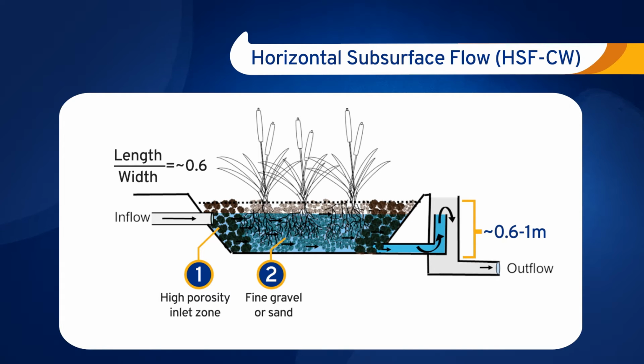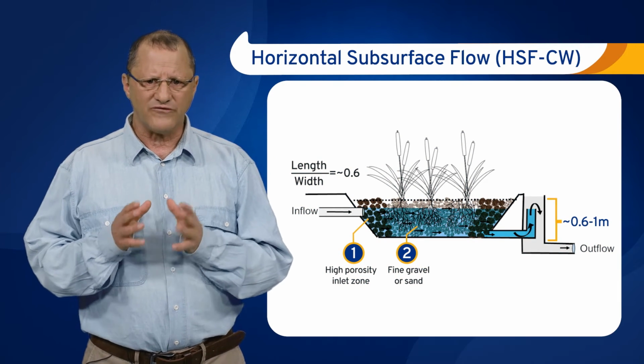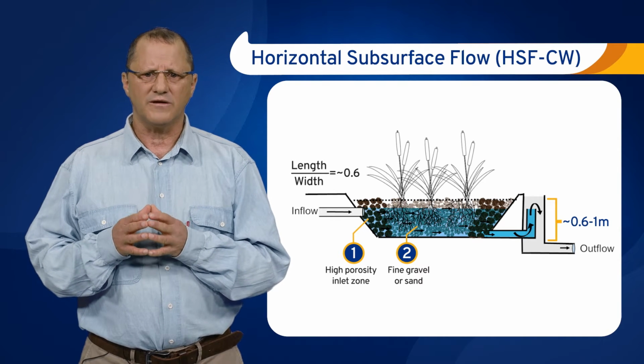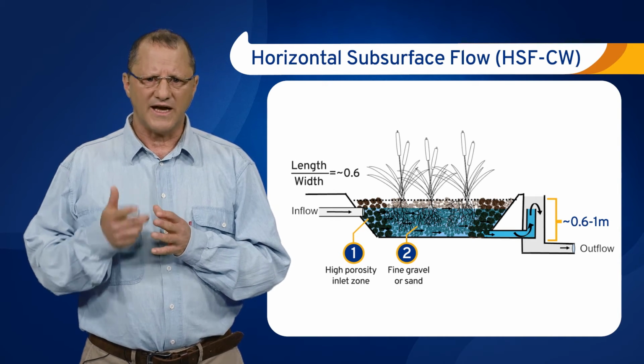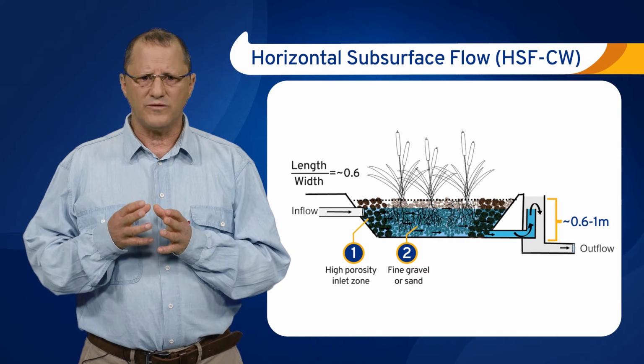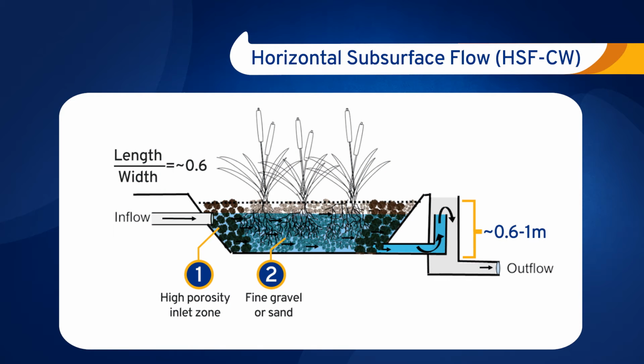This activity can be aerobic and/or anaerobic. While the role played by plants in these systems is still controversial, they are mostly considered to contribute to the water treatment through assimilation of pollutants, gas exchange, enhanced microbial activity near the root zone, and through moderating the water flow and temperature. The plants are also aesthetically pleasing and may reduce bad odors from the wetlands. The water exits the system via an outlet zone, which contains larger porous media.